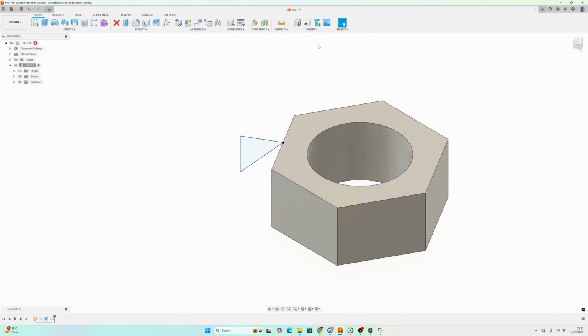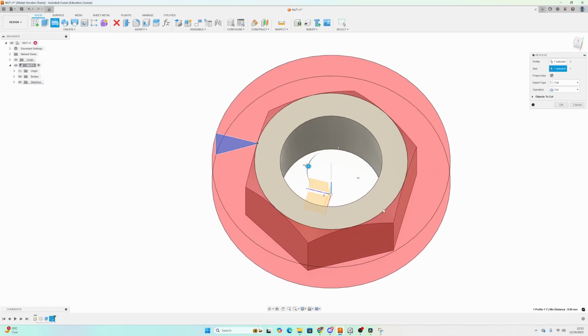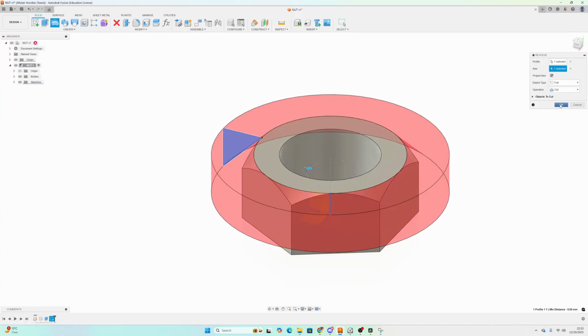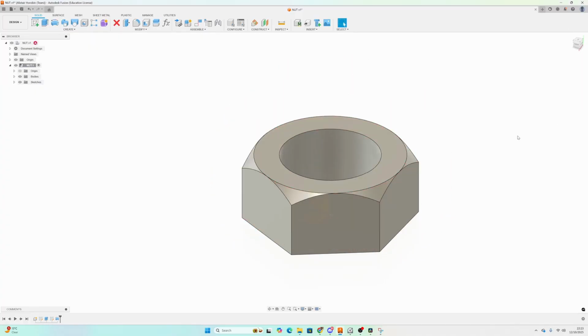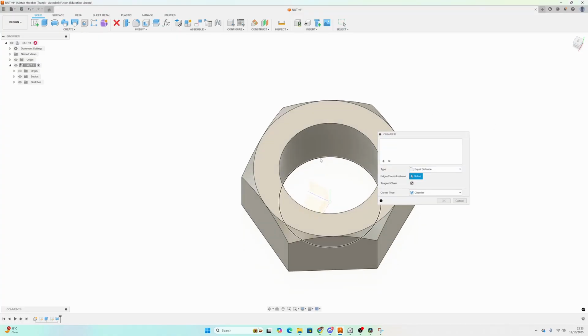So then we're going to finish sketch, go into revolve. Now, as you can see, it's already auto-selected this face. And now we're going to select our axis to be the y-axis, so that's this. And you can see it's already selected the cut operation. So when I click OK, you can now see it's already cut. Now before we do the threading, we need to add a chamfer. So we need to go into chamfer, select these two bottom faces, and give it a value of 0.5mm.